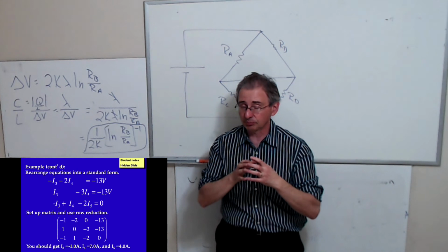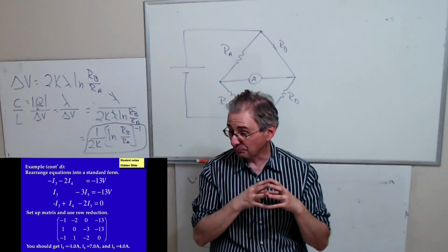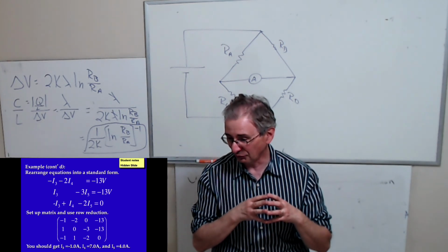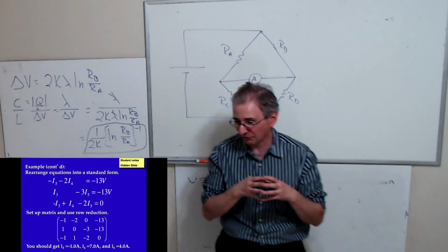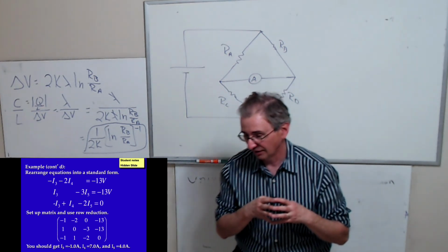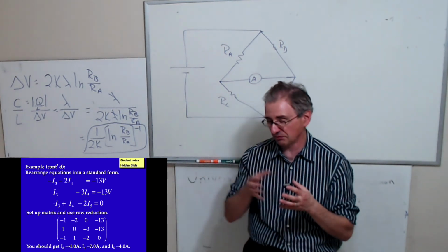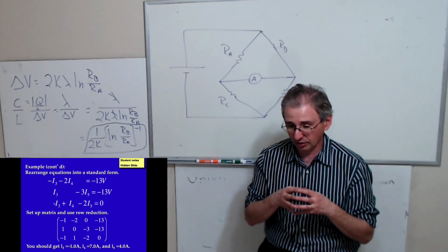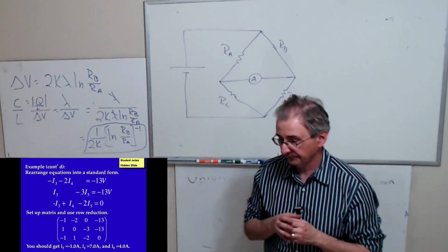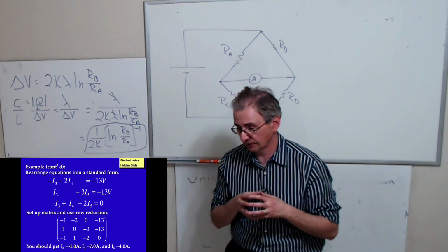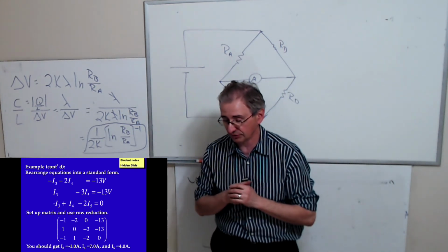To measure current, you put a resistor in parallel. Let's call it a shunt resistor. And I put a video on one of the modules where ElectroBOOM shows you how to do that. So when you take a resistor and put it in parallel to the galvanometer or even the ammeter, that resistor is called a shunt resistor, and you can use it to measure current. What that does is lower your resistance. And really what you're doing is measuring the voltage drop across that resistor.